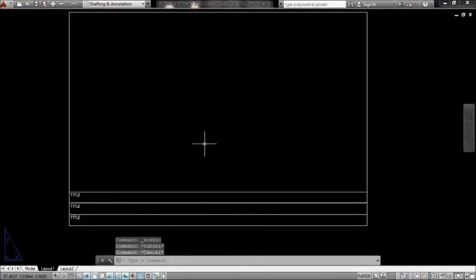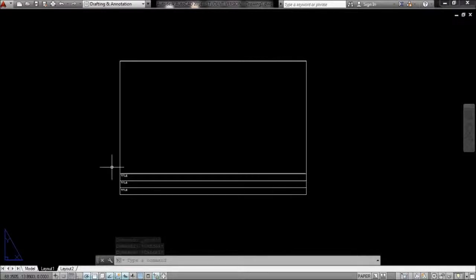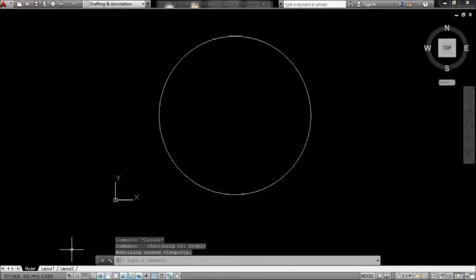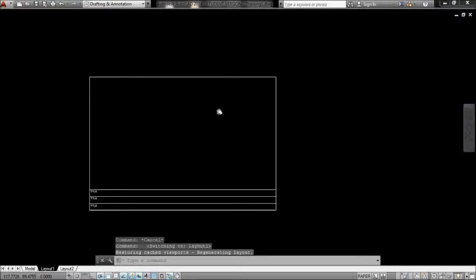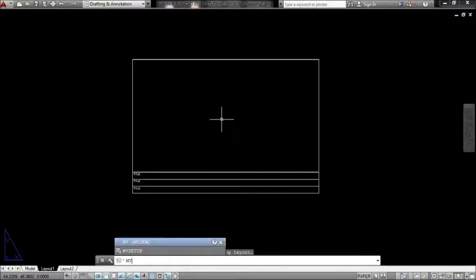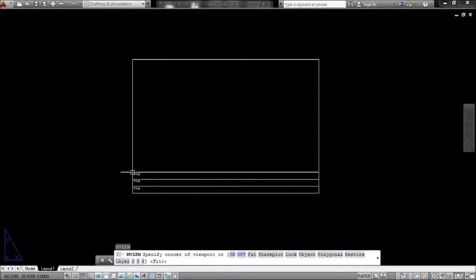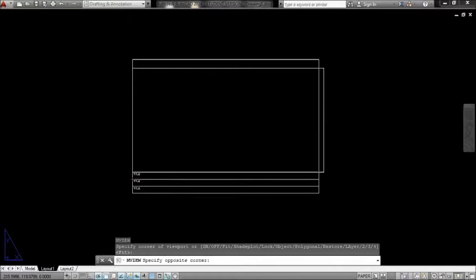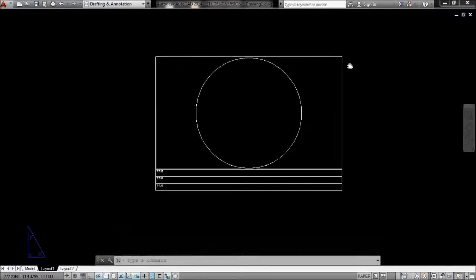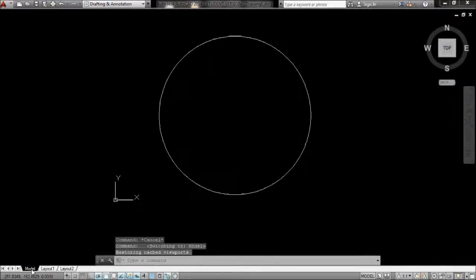We're now going to do a viewport. So imagine we've got the model here, what we've drawn, that's our 1:1 size circle, and the layout, that's our 1:1 size A4 sheet of paper. Just type M and V. We're going to make a viewport. If you remember that as a setup, MV, press enter, and just click here, snap to the endpoint, click here. That'll give us a window, if you like, through to the model space. We're in what's called paper space, and that's model space.